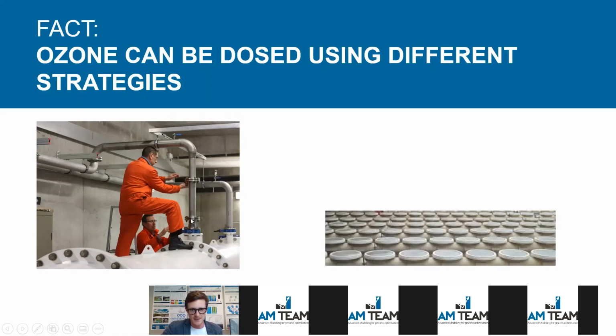So you have a certain side stream, part of your water you take out, you ozonate it, you inject a lot of ozone in it, and then you reintroduce the side stream in the mainstream. This is like a pipeline reactor, but you have different kinds of systems. That's one way, of course, many of you are familiar with it. The other way is bubble diffusion, fine bubble diffusion, also a very well-known way. Of course, they are very different.